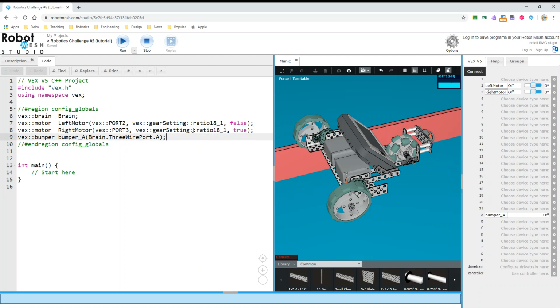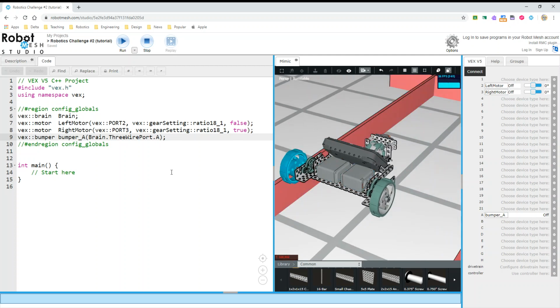So basically, with the left motor and right motor set up this way, you tell them both to go forward, and it will work properly, even though one motor is actually flipped upside down. That's what that is. When these are defined, we are giving them some values which are used to fully define the object, which is great because then we can do all sorts of great stuff with it. Once we understand what these things are and how they're created, you don't really have to worry too much about it at this point. Just trust that Vex is looking after itself here.